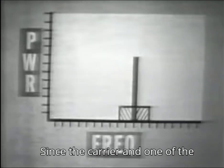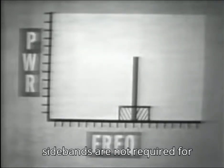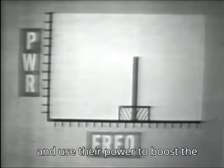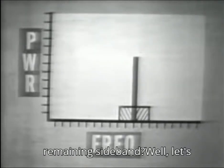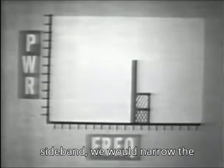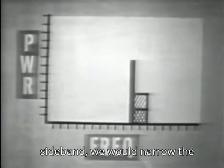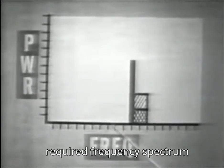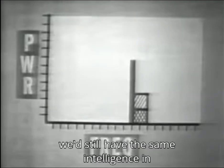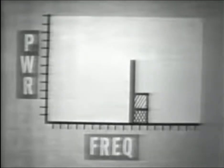Since the carrier and one of the sidebands are not required for transmission, why don't we eliminate them and use their power to boost the remaining sideband? Well, let's see what would happen. If we eliminate one sideband, we would narrow the required frequency spectrum by 1/2. And we'd still have the same intelligence in the remaining sideband.